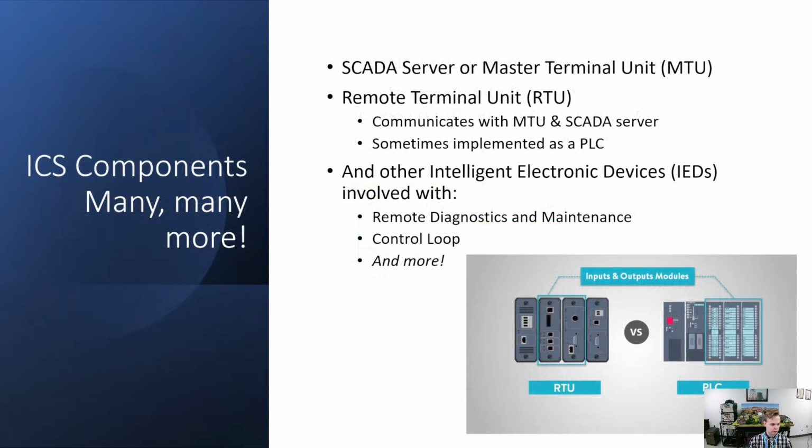And the list doesn't end here. There are many, many other components that go into these ICS systems here. Things like our MTU, our Master Terminal Unit. And this is what's communicating with a bunch of RTUs, or Remote Terminal Units, all throughout our system here. So these communicate back and forth, transmitting data and status information, possibly configuration information, to keep the system in sync. Sometimes these RTUs are actually implemented as PLCs themselves. So sometimes some diagrams will have a PLC, some diagrams might have an RTU, some might even have both.